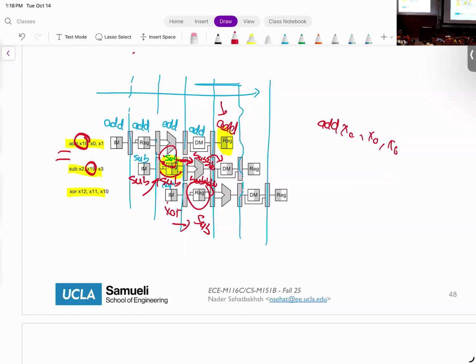So the question is, how does the hardware know what its no op is, how do we know it's x0, and why is it add x0, x0, x0? The hardware knows what its bubble is. This is something that you hard code in the hardware. As I said, some ISAs actually do have a specific no op. I think ARM actually has an instruction literally called no op, or maybe MIPS has it, I don't remember correctly. RISC-V doesn't have it. It understands the concept of no op, which is replaced by add x0, x0, x0, but it's hard coded in hardware.